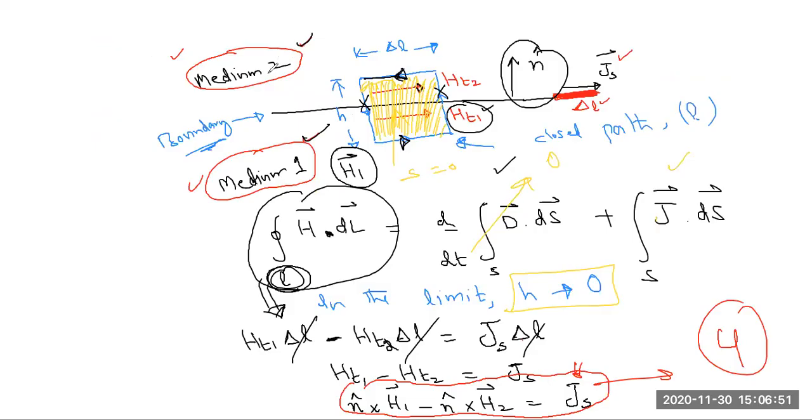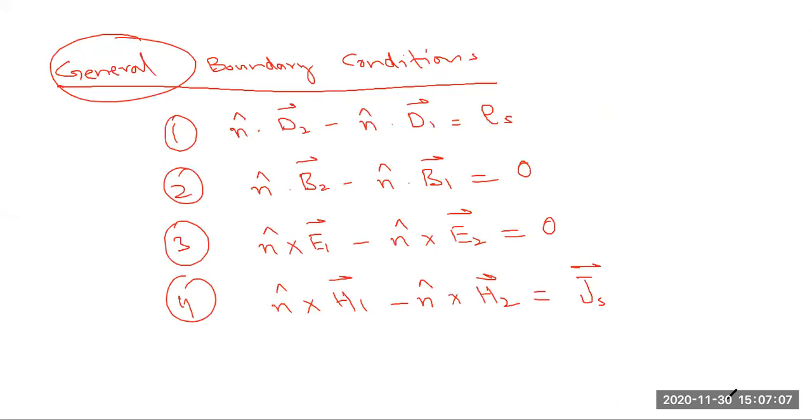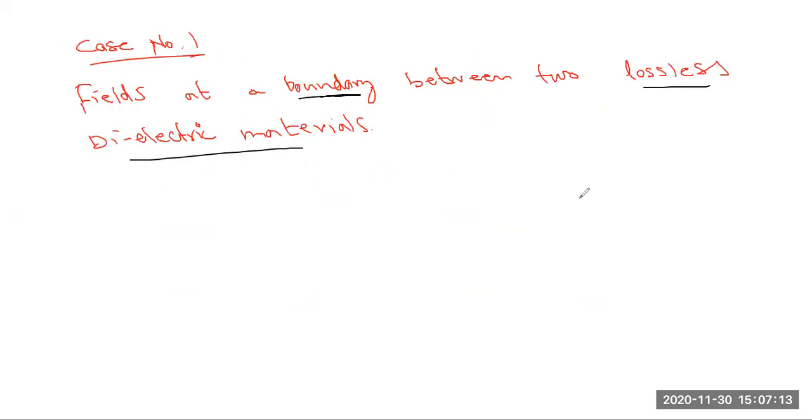Now, in my previous lectures, I mentioned this behavior, that is, medium losses are related to what? Can anyone answer this question? Conductivity, sir. Yes. So we mentioned this point that from the electromagnetic fields point of view, losses are related to the conductivity of the medium. Okay? If medium conductivity is zero, it means that it is lossless.